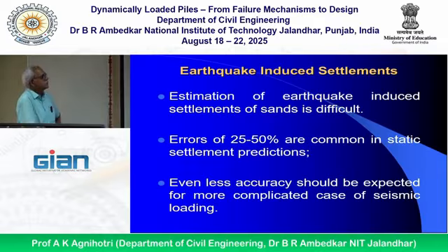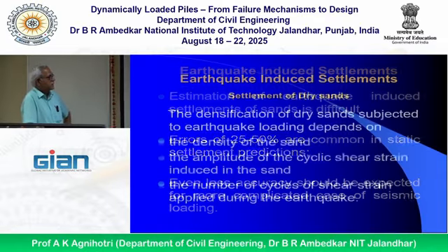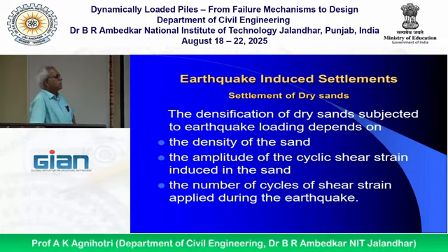Now, earthquake-induced settlements in dry sands. Densification of dry sands subjected to earthquake loading depends on the density of the sand, amplitude of cyclic shear strain induced in the sand, and number of cycles of shear strain applied during the earthquake. It will depend on these factors: density of sand, amplitude of cyclic shear strain, and number of cycles of shear strain applied.